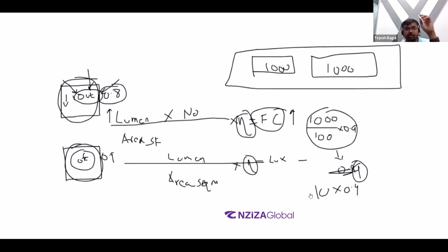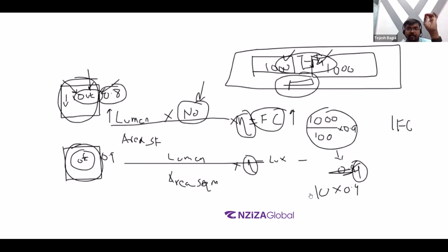Now going back to the average foot candles, till now we have spoken about the emergency or minimum foot candles, but when you have average foot candles, the same concept applies. Let's say you have 3 light fixtures and you have determined only 2 light fixtures are required to meet the criteria of, let's say, 1 foot candle. Then you will require only 2 given light fixtures to be on emergency. The third one you can keep on utility power or raw power, that is fine. But now we are talking about the minimum foot candle of 1.